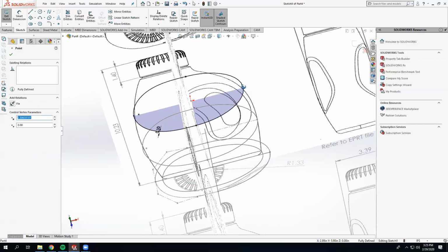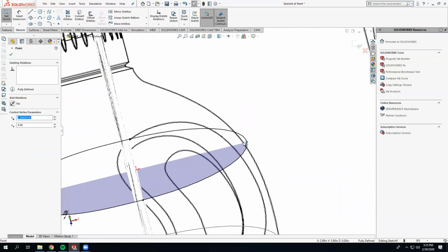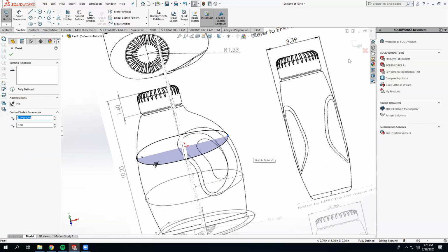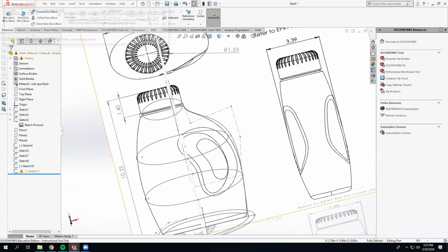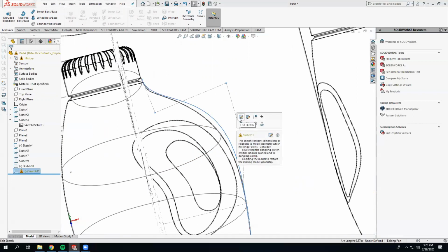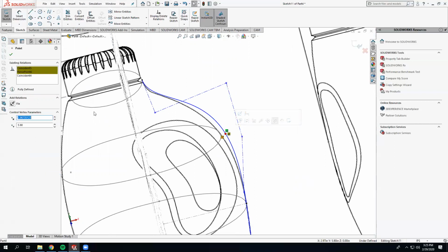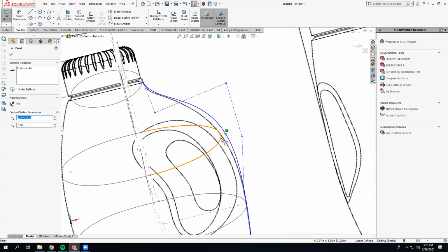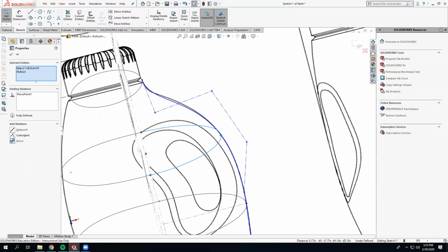And now I can move this one there, and I will definitely have an error message after I click exit, because I created a constraint here and now that line is gone, right? So I just need to recreate it. So edit sketch, this point, you see, it was coincident previously. So delete, delete, take this point and now attach it there. Perfect.